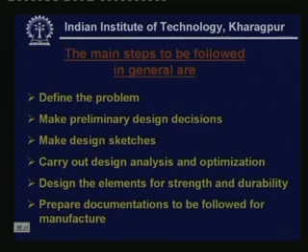Next, the main steps to be followed in general are: define the problem. First, you have to understand the problem. Make preliminary design decisions, which, as I have repeatedly told, is a very important factor. Make design sketches. Carry out design analysis and optimization. Design the elements for strength and durability. Prepare documentation to be followed for manufacture.